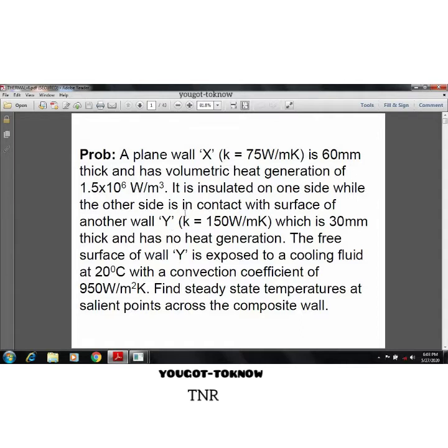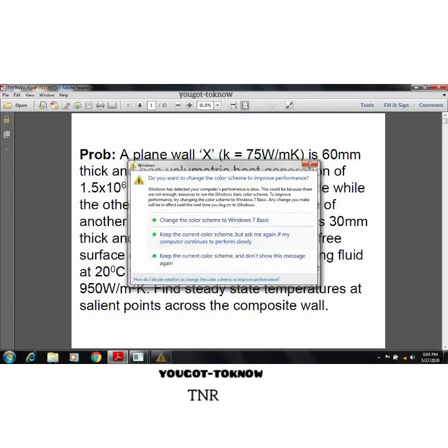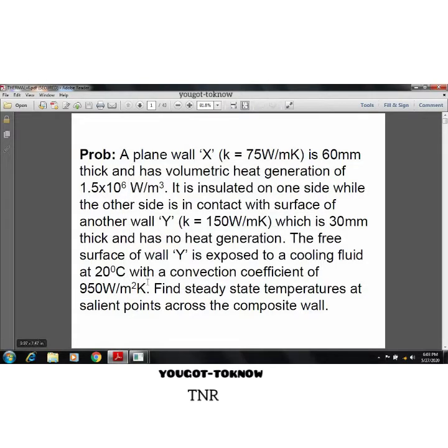If you observe, there we have only one slab. Here we have two walls, where the k value is different. When two walls are there in a 2D problem, how to construct this? That is one thing. Then heat generation is given for one wall, and not for the other. Apart from that, if you compare with the previous problem, we did not see the convection concept there. Now we are seeing convection here. How is convection given in 2D problems? In 2D we are not going to create any element with respect to convection; directly we can apply it. How to do this will be explained.